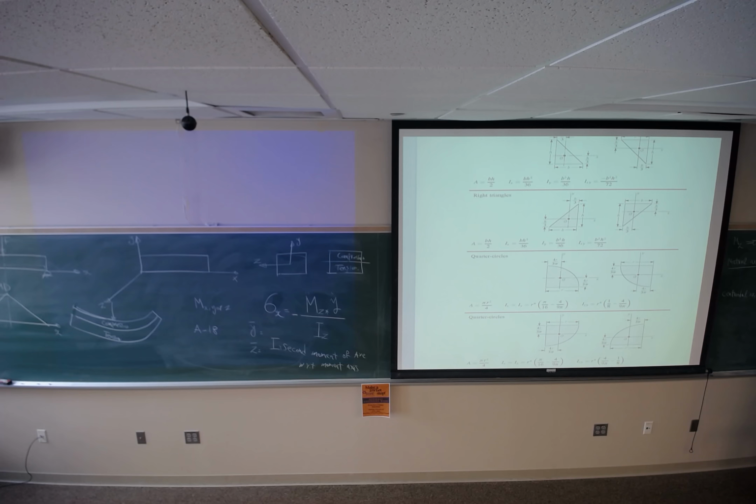We have the neutral axis, and we have the neutral plane. Whatever is the axis of moment is going to represent z, and whatever is the axis of the beam, which is x, is going to represent the neutral plane. So the plane passing through the neutral axis, just imagine a plane in the zx direction passing through this axis. It's going to be this plane.